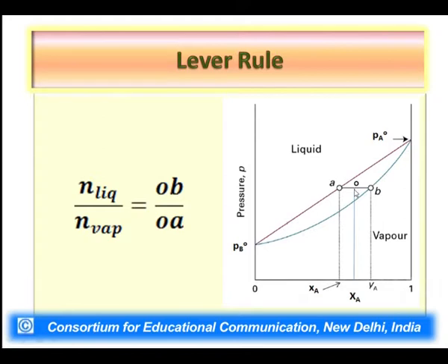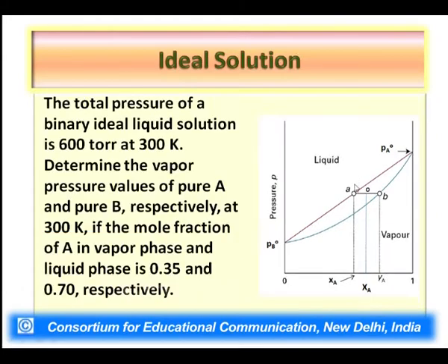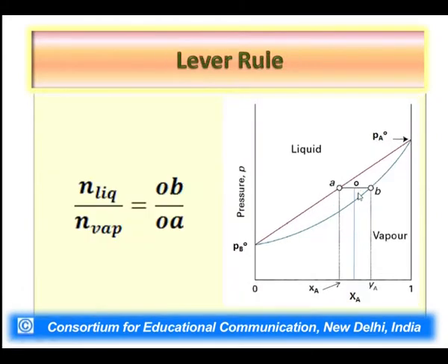From the discussion we have carried out so far, if we want to determine the amount fractions of A in the liquid and vapor phases, then we should draw a horizontal line, called the tie line, to connect the two different phases, liquid phase and vapor phase, and these two points on the horizontal line are called point A and point B.